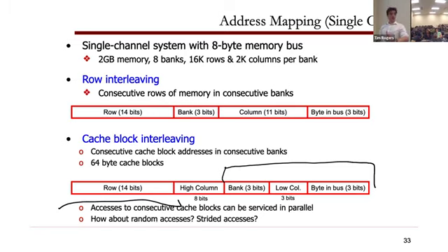So every cycle you can only do 1. So there's a select. Basically, it's saying which bank I'm selecting this particular cycle. So I'm command limited in that way. Now maybe some memory, this would depend on the implementation of the memory technology. I think some of the higher bandwidth memory technologies allow for multiple bank RAS signals, but the typical flow in standard DDR is 1 RAS at a time for 1 particular bank at a time.